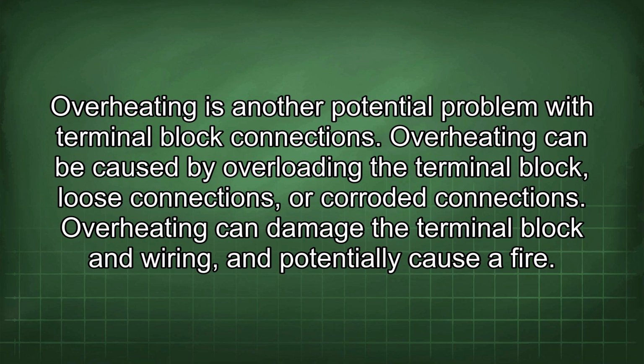Overheating is another potential problem with terminal block connections. Overheating can be caused by overloading the terminal block, loose connections, or corroded connections. Overheating can damage the terminal block and wiring and potentially cause a fire.